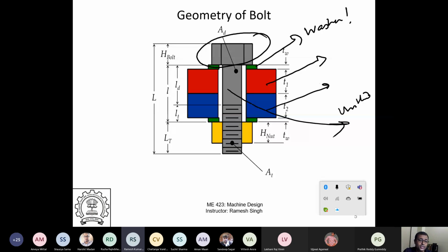We actually have these measurements for the pitch diameter, which I'll teach you a little bit about. But if you would have seen in the lab, you would know what a pitch circle is. How do you measure the pitch of a screw? Those things are there in the metrology lab. And one of the things you've gotten right is that the diameter actually is smaller than the effective diameter in some sense, right? Because there are these grooves for tightening. So the effective diameter will definitely be smaller than the unthreaded portion. So I should have as much unthreaded as I can.